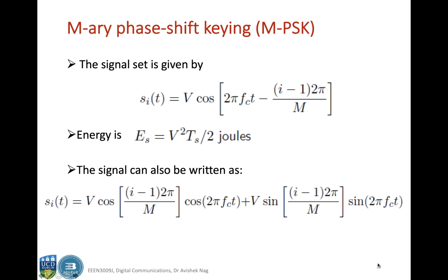So in this lecture we will start talking about M-ary phase shift keying. In the previous video we started discussing M-ary signaling techniques in general, and then we were discussing M-ary ASK. In this lecture we will talk about M-PSK. The general expression for a signal in an M-PSK is given by this.